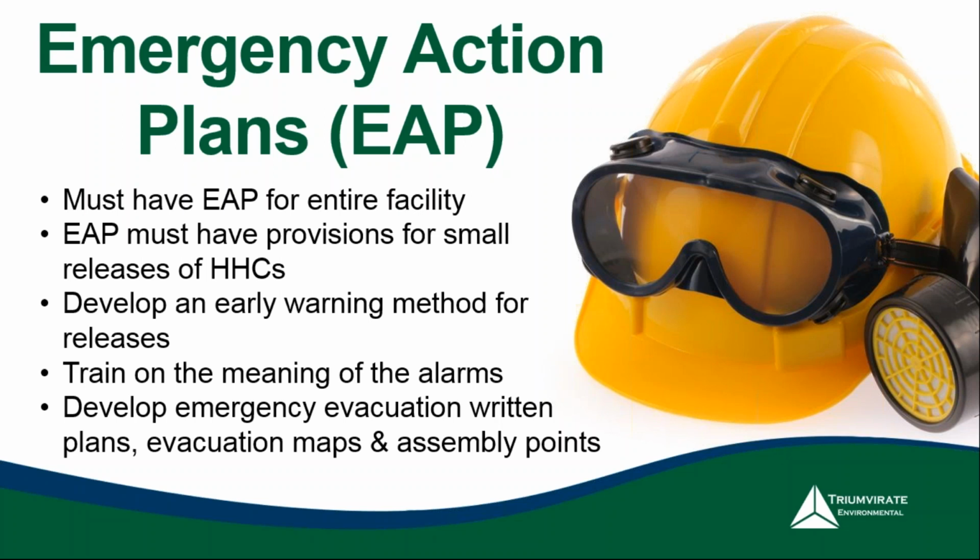Did you think about whether this process could rupture and leak, and it could actually go into one of those routes of egress? Well, that's got to be documented in your plan, to say, okay, we're going to have to redirect people to a different route to ensure that they're not literally going right through the release area. So these are some of the things that you want to take into consideration here.